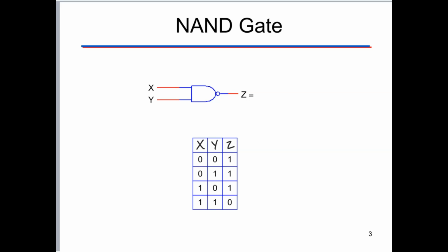First, let's talk about the NAND gate. And a NAND is literally just the opposite of an AND. So that means that we can write the logic expression as XY here, but then invert that output, or the opposite of an AND. And through De Morgan's, we know that we can write that another way as X' + Y'. Break the line, change the sign.